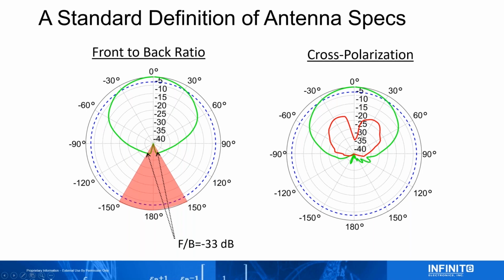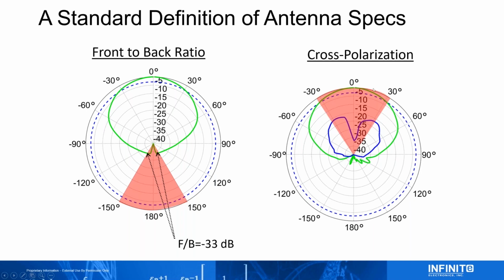So looking at the definition here, if we just said at 0 degrees, oh, the cross-pol is 32, but really, I'm not using this sector just at 0 degrees. I'm using it over an arc, 60 degrees, 65, and I care about the cross-pol discrimination over this entire arc. So you look at the maximum value, and here we're at 18 dB, and this is the value that should be reported on the data sheet instead of just that 32, and it's a more accurate representation.